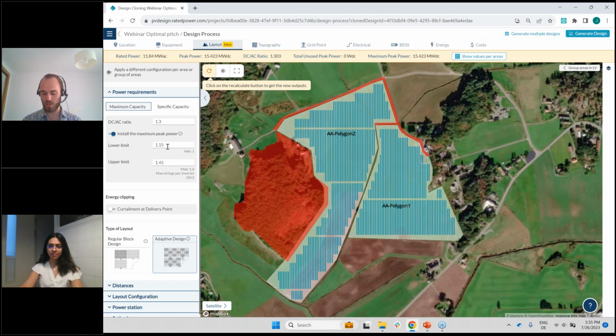So based on how your tilt is, how is the shadowing overall, how much energy do you get out of it? And if I'm just thinking, of course, if you have a certain DC-AC ratio, it might be the case that at low sun elevation angles, you have not the optimal voltage for the inverter. So now I have to actually rethink my answer, because I think that could be an effect.